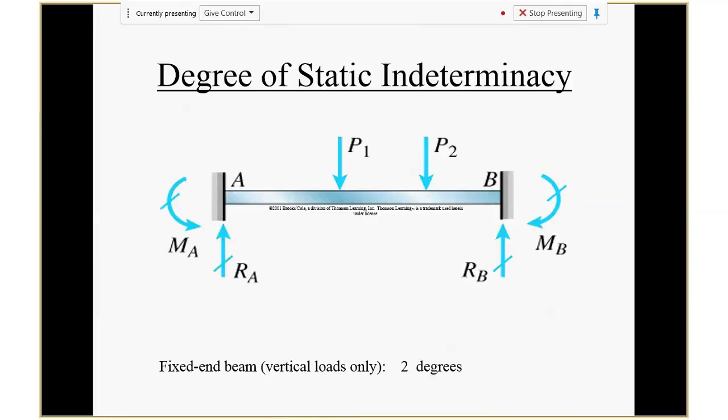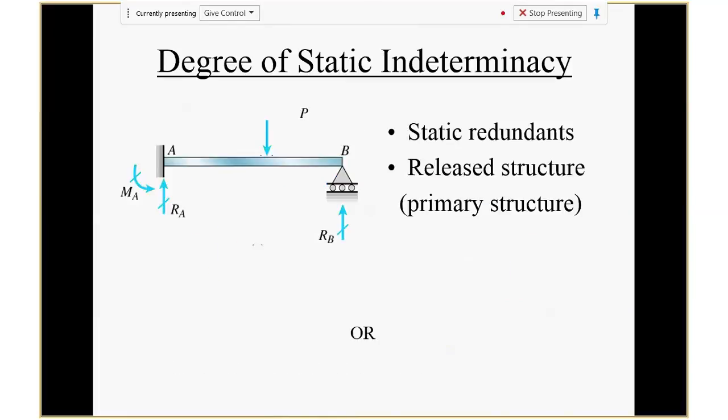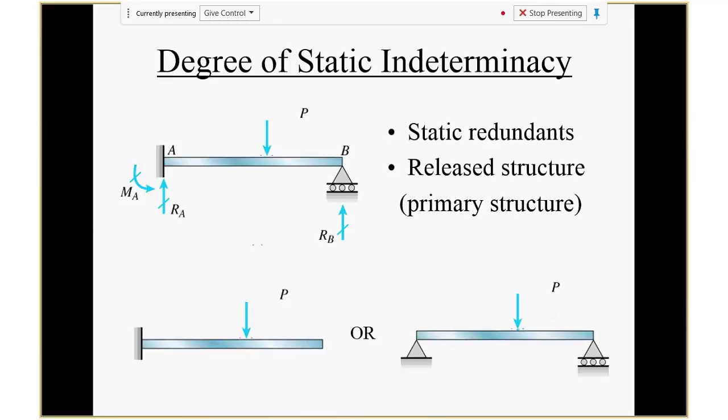Okay, so we talk about the degree of the indeterminacy. Okay, here is another concept. When you solve the indeterminate beam, the way to solve it is you remove the redundant restriction, treat it as an unknown force or unknown load, and then you solve the equation based on this as a determinate structure.